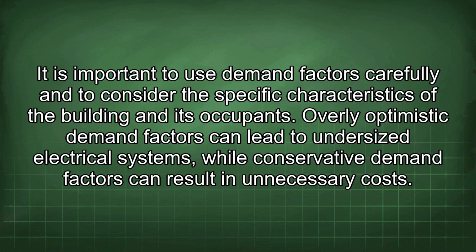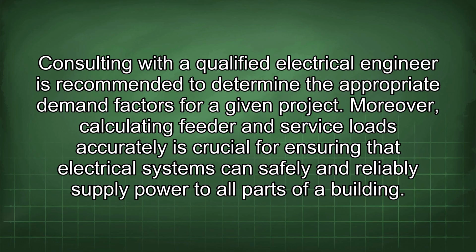It is important to use demand factors carefully and to consider the specific characteristics of the building and its occupants. Overly optimistic demand factors can lead to undersized electrical systems, while conservative demand factors can result in unnecessary costs. Consulting with a qualified electrical engineer is recommended to determine the appropriate demand factors for a given project.